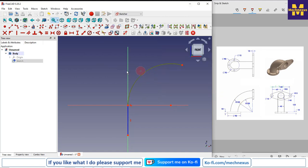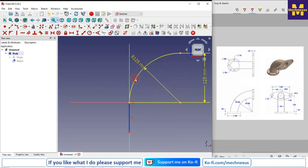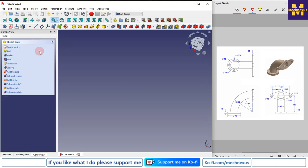Now I will give my dimension, which would be the R125, and we can see that this height is 125, so I will select this point and this point, and I will give my height 125, and I will also make it construction. Now this is our swept profile, and now I will come out of the sketch.